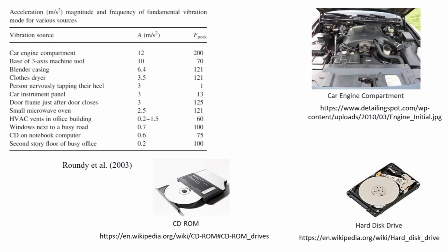Also, undulation in the ground is sometimes transmitted to the vehicle. So, you have to make your suspension system in such a way that these ground vibrations will not be transmitted to the driver. While designing the automobile, all this vibration aspect has been taken care of. Due to wear and tear in the tire or in different parts of the automobile, sometimes the vibration will be severe. At that time your analysis will no longer be valid in the linear range, and you must go for the analysis by taking the system to be nonlinear.